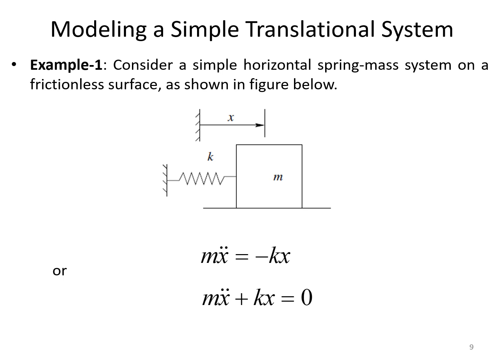Now, consider a translational system with a spring and a mass like this. Now you have a force which is applied in this direction. So if I am applying a force here, since the motion is in the linear direction, in case of translational mechanical system, the force is taken as equal to mass into acceleration. Acceleration is nothing but second derivative of your displacement. So m into d square x by dt square is taken as equal to minus k into the displacement x.